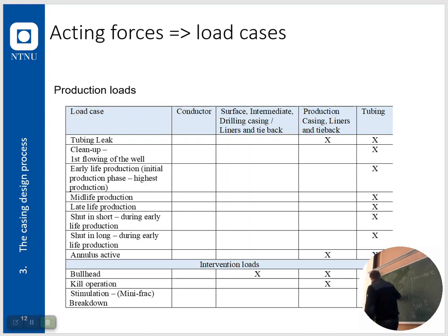Remember last session when we looked at how these things interlock. The PGB, permanent guide base, looks like this with the conductor sitting in it like this, and then the wellhead comes in like this with a 20-inch surface casing inside, and they lock together here. In principle, what we saw on land-based wells, the starter head in the previous slide, is basically the same.